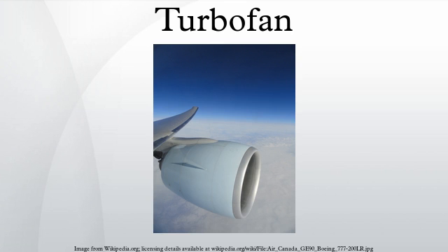The Rolls-Royce Conway, the world's first production turbofan, had a bypass ratio of 0.3, similar to the modern General Electric F404 fighter engine. Civilian turbofan engines of the 1960s, such as the Pratt & Whitney JT8D and the Rolls-Royce Spey, had bypass ratios closer to 1, but were not dissimilar to their military equivalents.